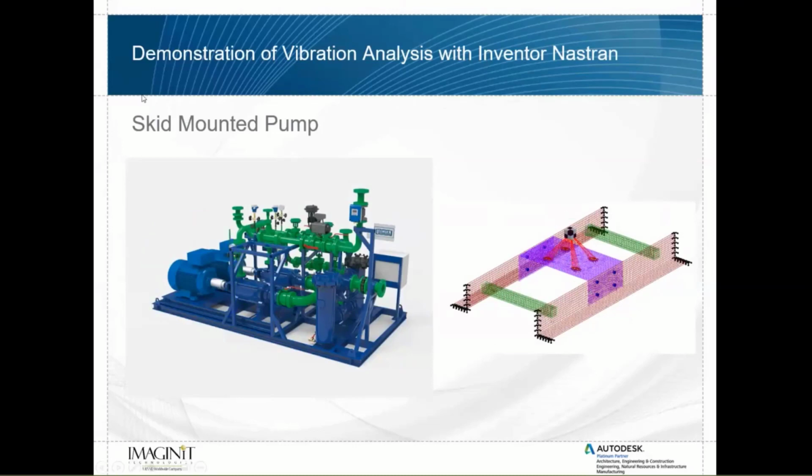I'll walk through what I set up for this analysis. Number one, because I will be getting some vibration from that pump, I'll likely want to run modal analysis and make sure that I'm not near that natural frequency. I'll probably want to run frequency response because, due to the vibration of that pump or the motor, depending on what I'm mounting here, I'll likely see some sinusoidal excitation.